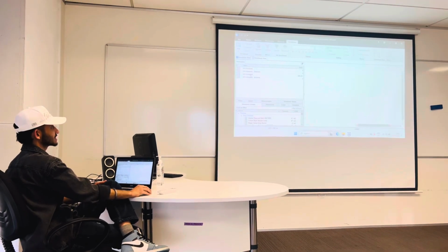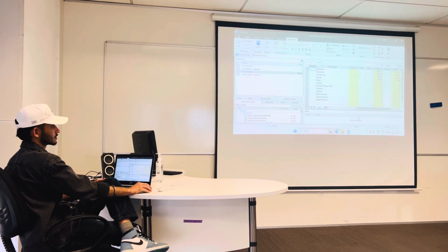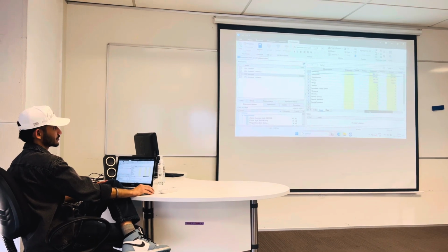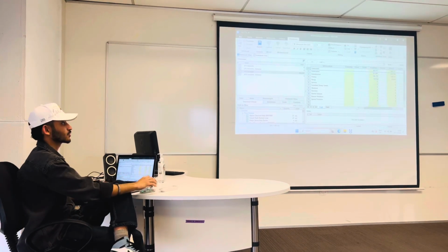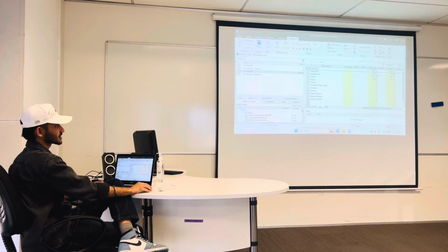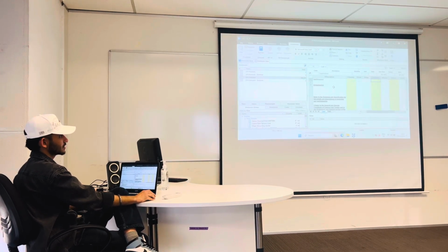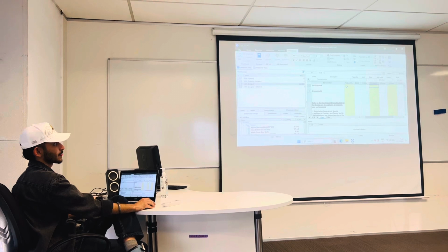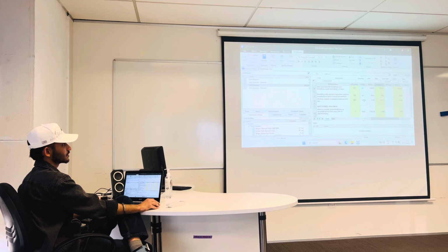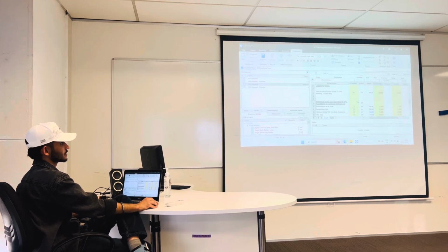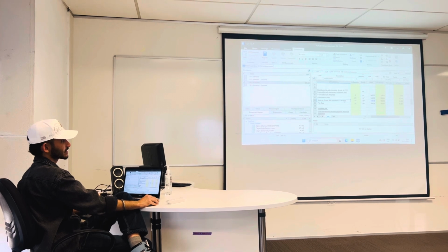In SOQ we have GFA group, in which do you remember we calculated the measurement for the slab, concrete slab? So it's in substructure, where we will double click, and we have all the details here. Description of the work, quantity, unit, rate, and then subtotal. So for example, in this point, slab on grade 500 mm thick column.